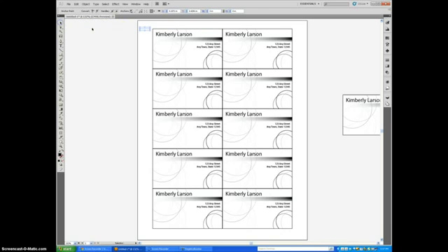the shift key. Now I want to take this trim mark and make it into a stroke instead of a fill. I'm going to hold down the Alt key and shift and pull it to where it intersects with the line underneath it. Now one of the cool things about Illustrator is because I made that move once and I went down 2 inches, I can do Control D for duplicate and it will continue down the page.